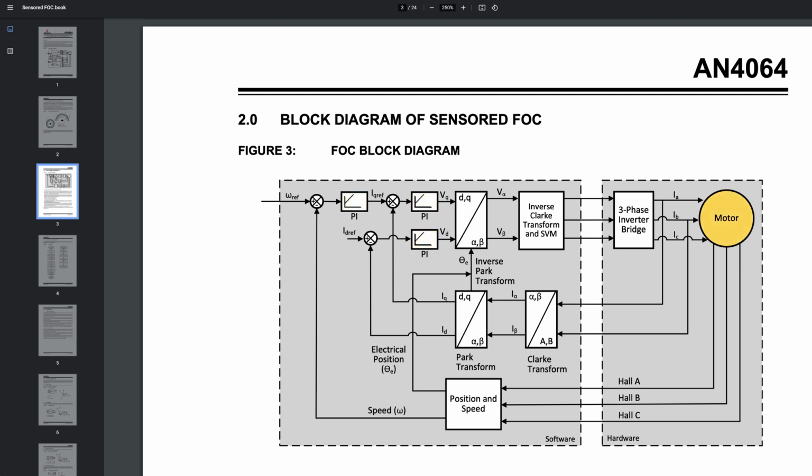So the motor has position feedback coming in. The motor also has current feedback. All three phases that a BLDC motor is driven through are consuming current. You don't have to measure all three phases in a FOC because technically the summation of all three phase currents sums up to 0. So if you measure 2 out of the 3, you can always estimate the third one.